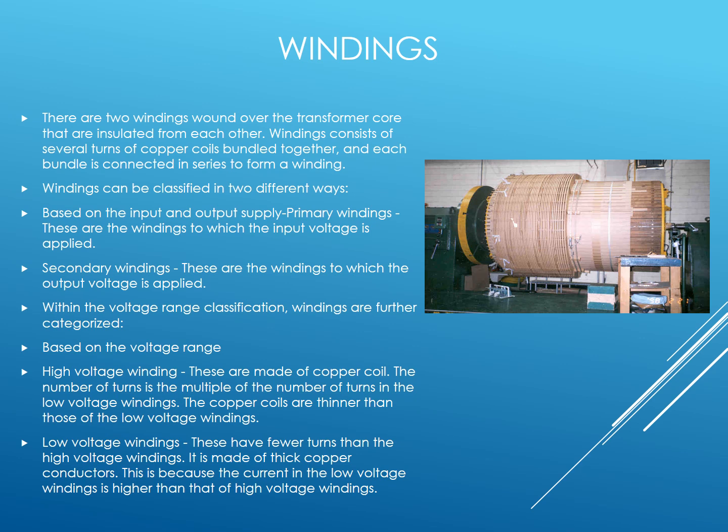In this, how the windings are arranged is, low voltage winding is placed nearer to the core for easy insulation from the core, and high voltage winding is placed after it. Both the windings are on the same limb to reduce the leakage flux.